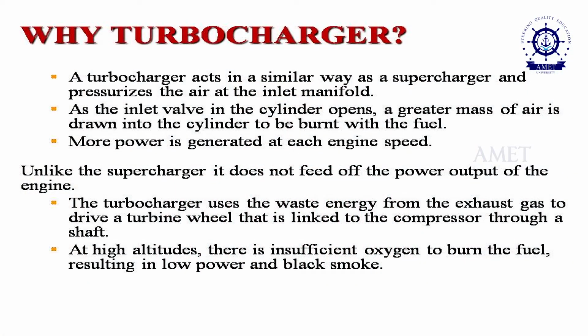The third mechanism, which probably is the most intelligent and efficient, is why not use the gas which is coming out of my cylinder, which is going to get out of the cylinder and go into the exhaust as waste gas. So, effectively I am going to use the exhaust gas coming out of the cylinder to rotate a gas turbine, which has a blower attached to it. So, basically I am not spending any energy to rotate that turbine, and the blower attached to the same shaft will then rotate. So, let us understand this a little better.